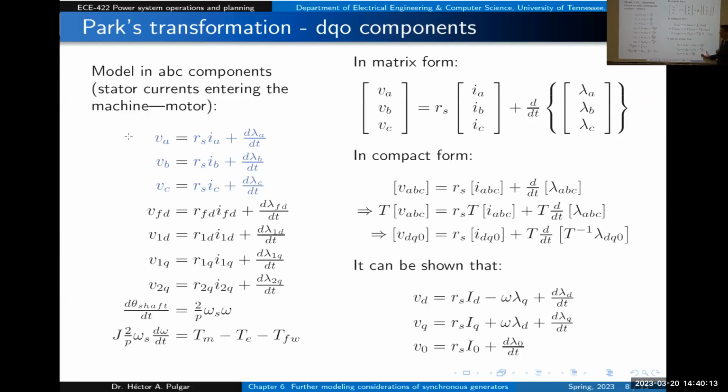We did have that with the signals for A, B, and C voltage and current, and that can be tedious. Here, we got rid of the direct dependency on time. And this is way simpler to model and to analyze. So right here, if we replace this equation by this, that's basically the park transformation in the new model.